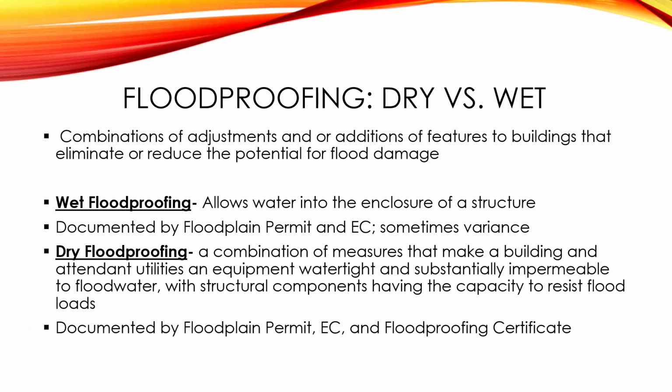So obviously, wet versus dry, very different. I feel like it's kind of a misnomer to call them both floodproofing. But floodproofing is defined as a combination of adjustments or additions of features to buildings that eliminate or reduce the potential for flood damage. So it's just two very different approaches to that.